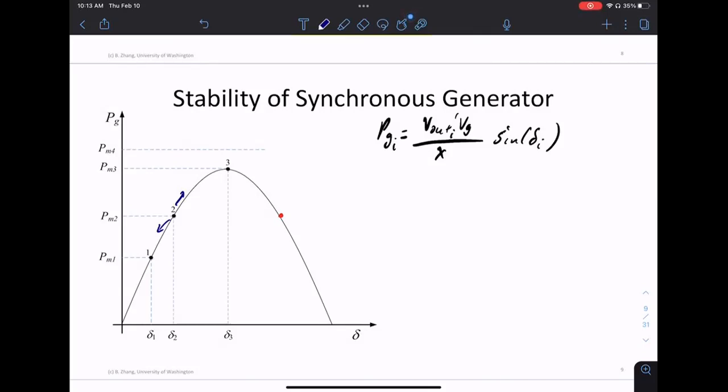Is there some advanced stability without a feedback controller? Is that stable by itself? No, you need a feedback controller, because if you have a generator, you need to increase or decrease the amount of power you're putting into it. Say you have a coal generator, or anything that boils water. Fundamentally, you need to open and close a valve of the steam that goes into the turbine. That requires a feedback controller.